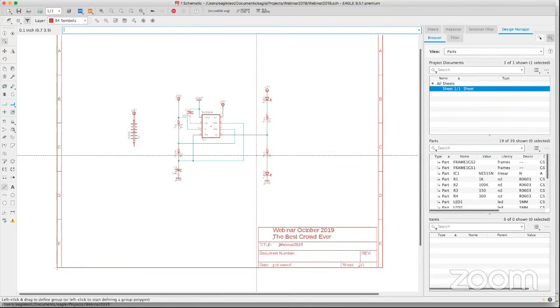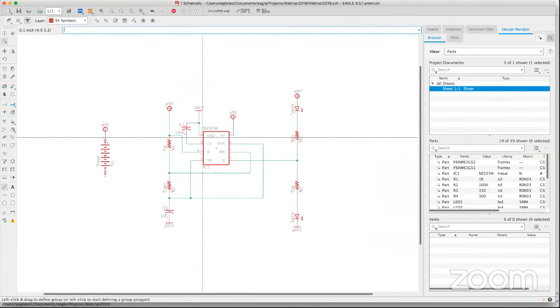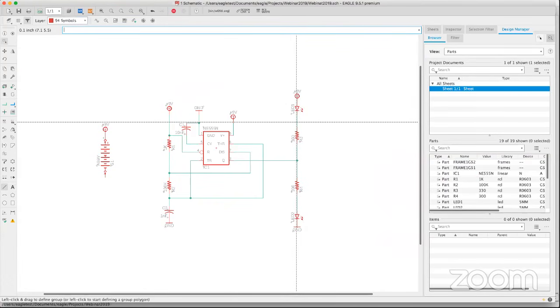In Eagle, in addition to using supply pins to distribute your power, if nets have the same name, even though they're not physically connected on the drawing, we just want to let you know that if I have 2 nets and each net is called MISO, they're going to actually end up connected when you go over to the schematic. So nets with the same name will always be connected.